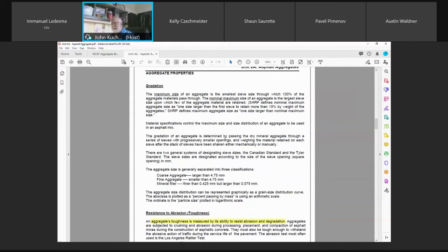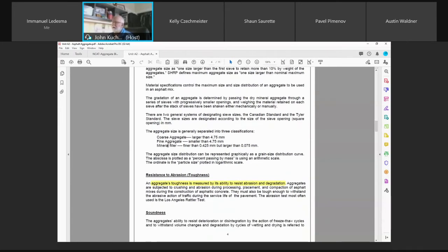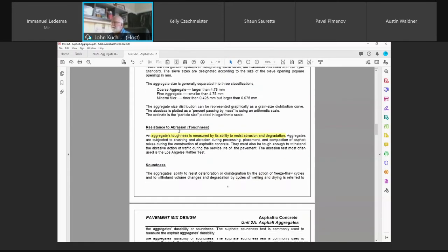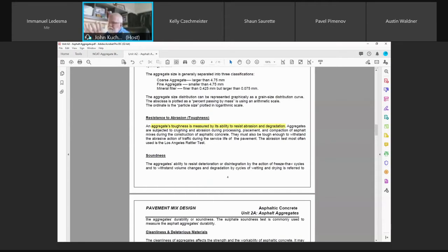And with the asphalt, as you're compacting, as you're rolling, you want the aggregate interlock. That's how asphalt works as compared to Portland cement concrete, where you want a coating around every individual aggregate. Yes, you need a coating of asphalt cement around every aggregate, but it's the interlocking of the sharp angular edges and the rough texture that binds the cement to the aggregate. And again, this is the same as we talked about. We have coarse aggregate, we have fine aggregate, we have filler. You know how to plot it.